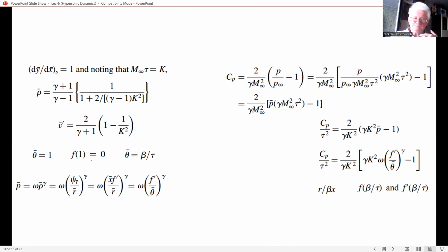The value of this yields the ratio of wave angle to cone angle. And in my opinion, for pedagogical reasons, we have deliberately chosen not to follow Van Dyke in this regard. Instead, we maintain a consistent usage of the body slenderness ratio tau instead of beta. Okay?